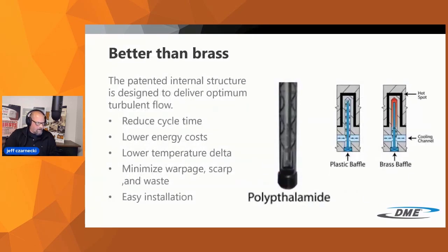DME a little while ago did introduce the plastic baffle. We got a patented design here. We have some features that help provide consistent turbulent flow as these waters reach standing cores and standing cavities. This will definitely help you reduce your cycle time, reduce energy cost, maintain a lower temperature delta, eliminate scrap, and it's also very easy to install.